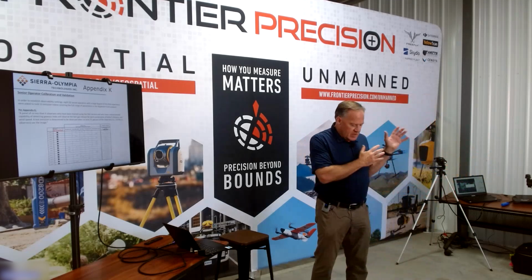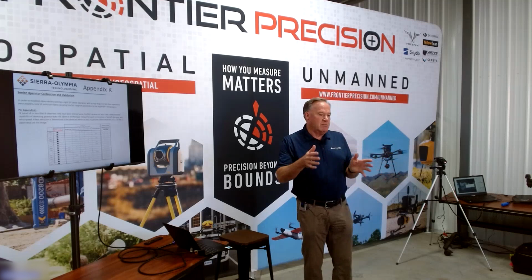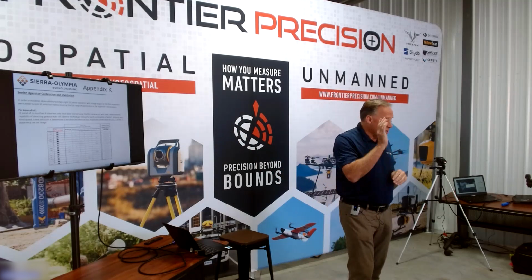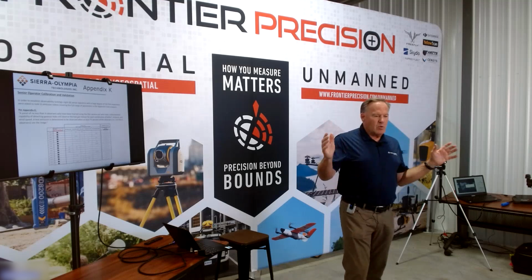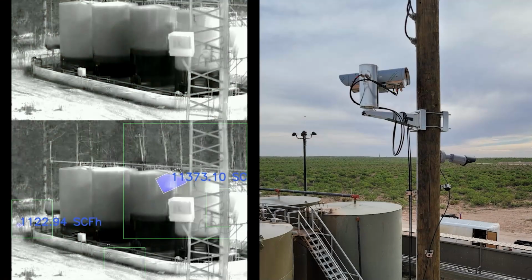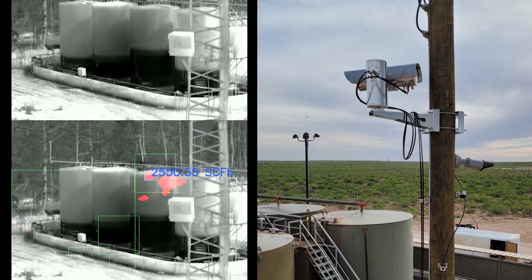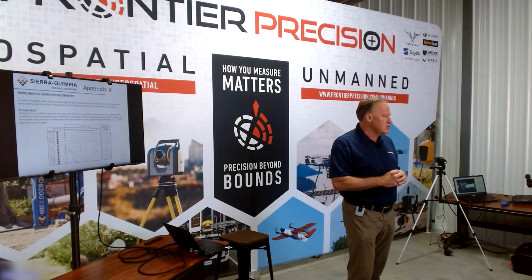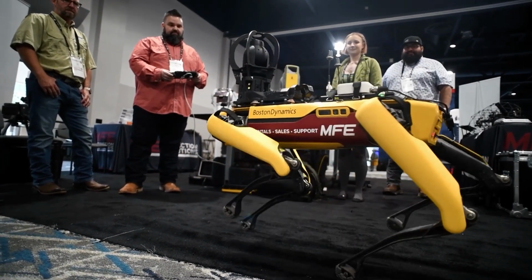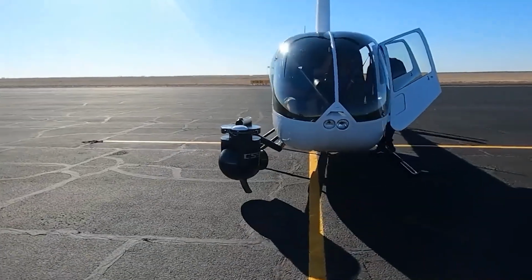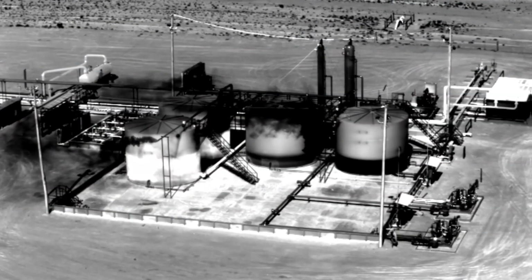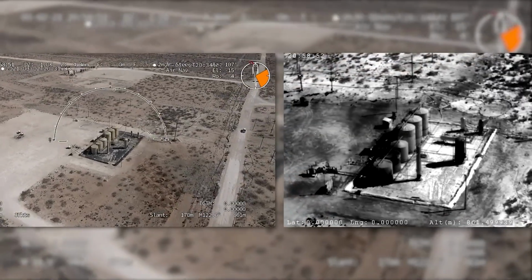Now the EPA and your air quality boards are asking people to define this so that they know that when the operator goes out to do an LDAR inspection, they know what the limitations of their product is. And this goes for aerial, goes for handheld, it goes for fixed mounted continuous monitoring, whatever OGI camera, and whatever application. If it's on a robot, any of those things, you have to establish how and when you're going to be able to use that camera and successfully, if needed, you would be able to find a 22 gram per hour methane leak. That's the whole purpose of it.